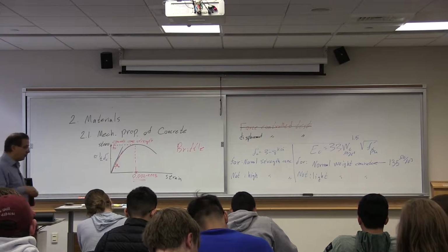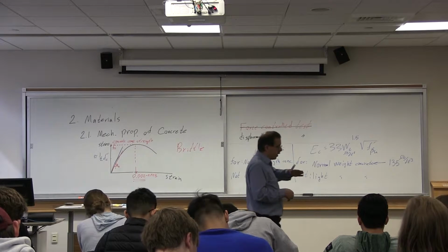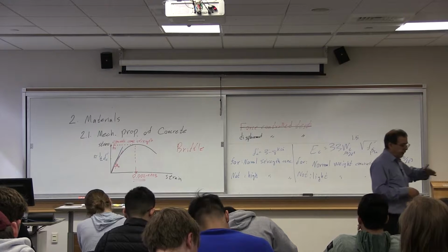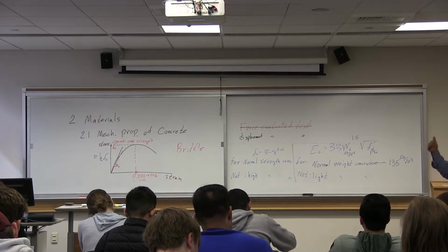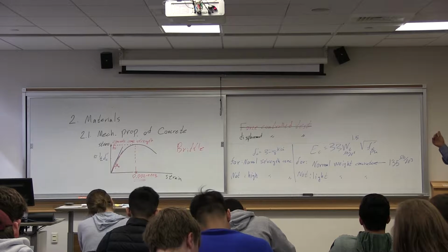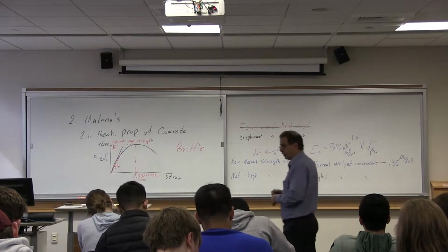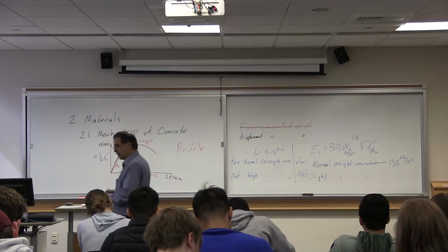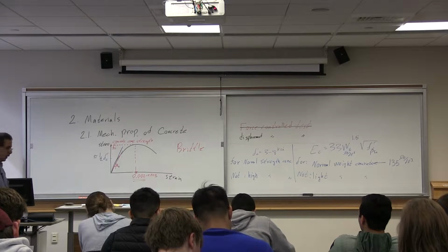Usually we don't have like 9 ksi, 10 ksi. Usually if it's not normal strength concrete, then there is a jump. You go up to about 11, 12 or more strength because you change the way you construct, and that really changes suddenly the strength of concrete.